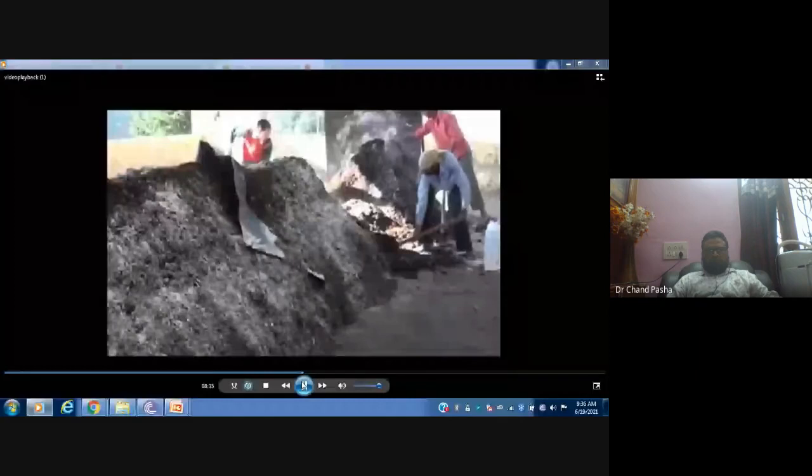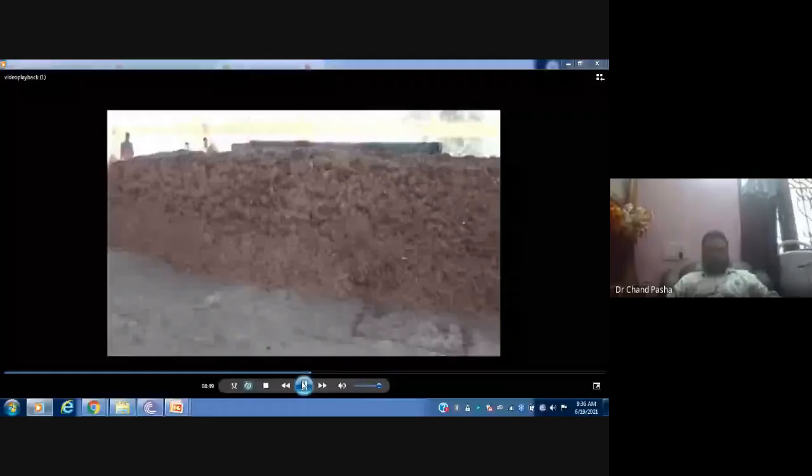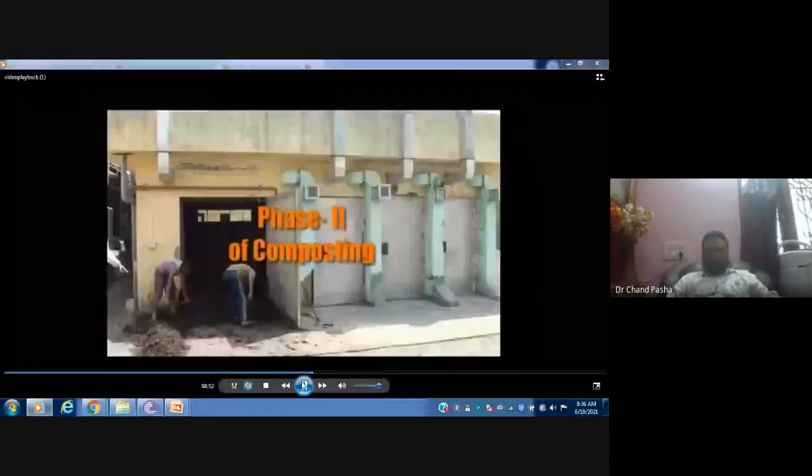On the 8th till 10th day, the pasteurization is performed in the pasteurization tunnel. Fill the tunnel with compost up to a height of 2 to 2.3 meters, manually or by filling line or bobcat. Install thermometers, one probe each in the plenum, in the compost, and in the air above the compost.